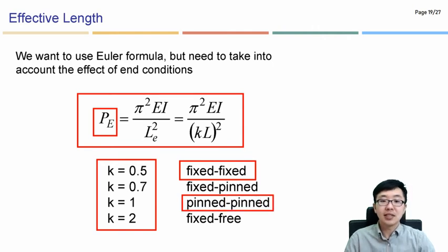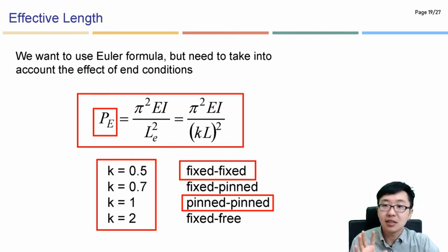So even if we use exactly the same material and same length, based on the boundary condition, we can make major changes in the structural capacity subjected to the actual compression. This is my main point from this lecture, topic 11, the importance of the boundary condition. So that is the judgment by our engineers.